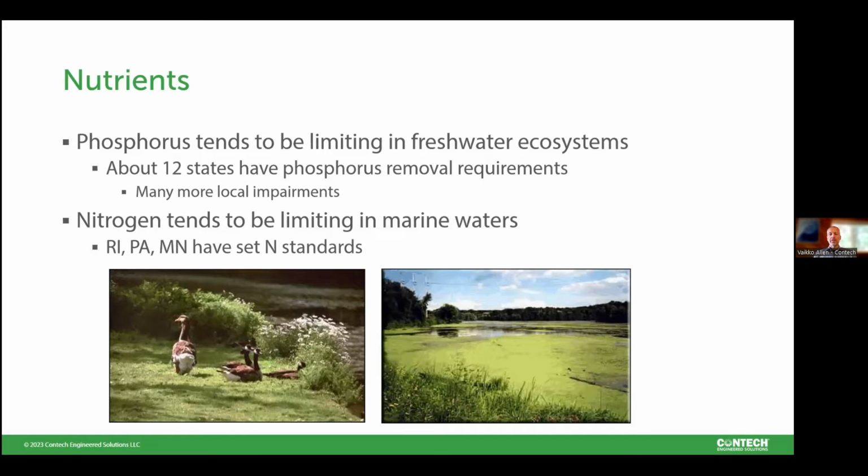And then when the algae dies, it goes down to the bottom and all the microbial activity digests it, and the dissolved oxygen levels get depressed, and then fish die, and it's just a bad scene. So to try to get around having these kinds of eutrophication impacts, we try to keep our phosphorus levels lower in stormwater than they would be without controls.